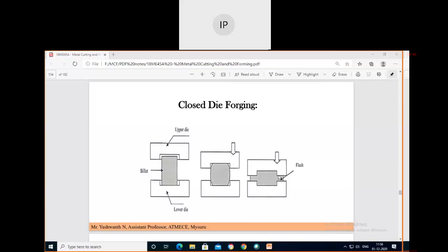The desired final shape cannot be obtained by forging the workpiece directly into the die cavity. Instead, some pre-forging steps are always necessary, and these steps can be completed using open die forging or impression die forging process. These processes bring the workpiece much closer to the final configuration, which is then completed with the help of the closed die forging process.